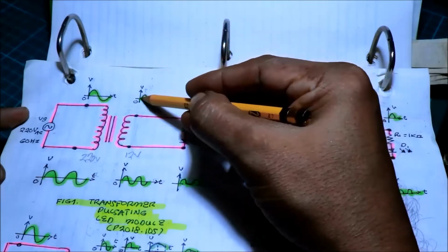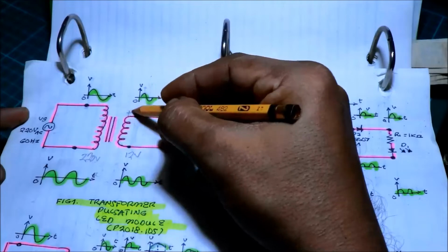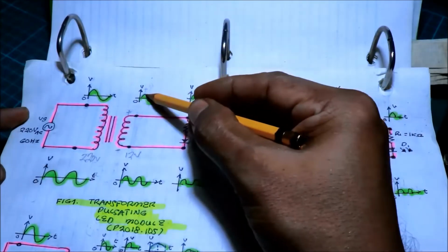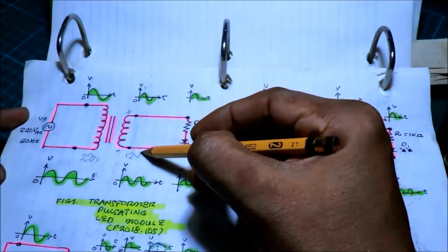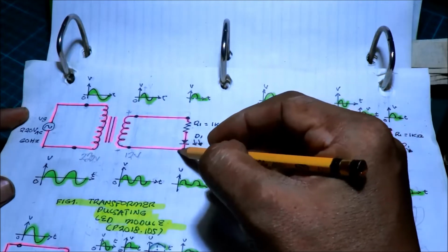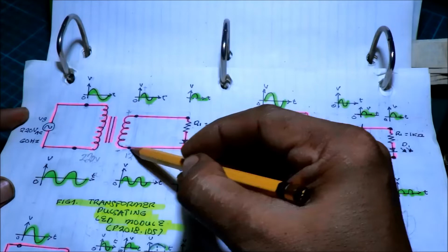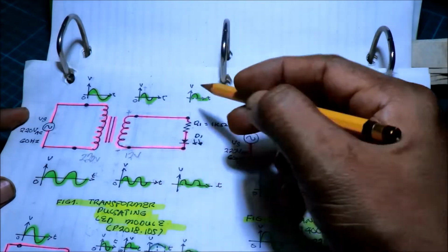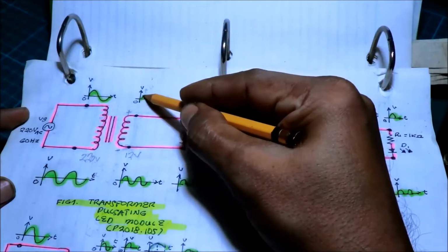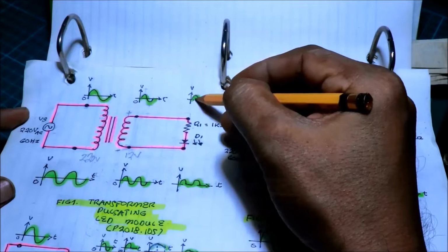During the positive half cycle, this terminal is positive and the other terminal is negative. So this small sine wave, which is 12 volts, will travel into the resistor and to the LED and go back to the other terminal. So we got the complete circuit. Because of that positive half cycle, it has an output, this one.